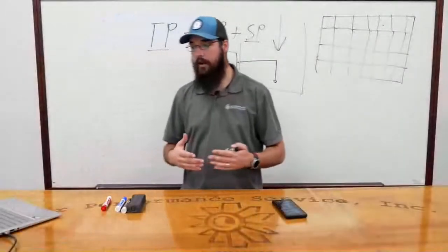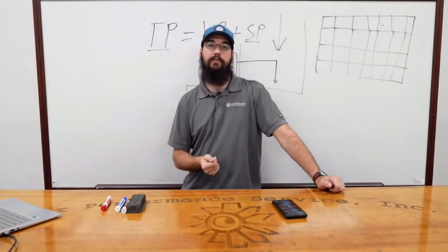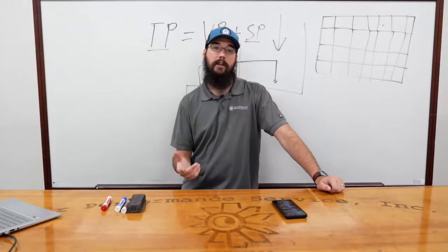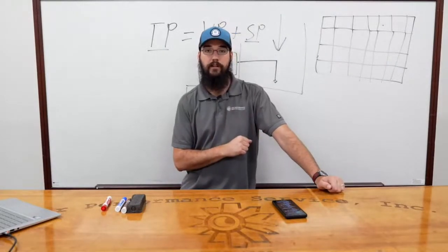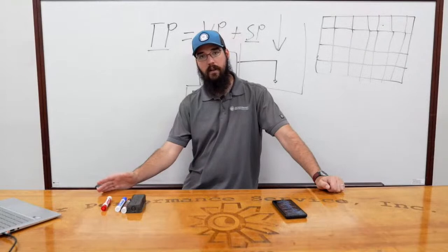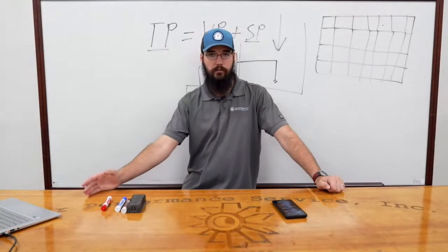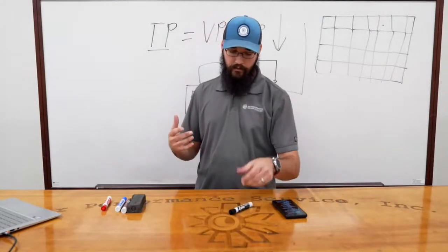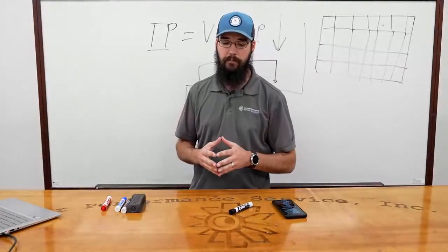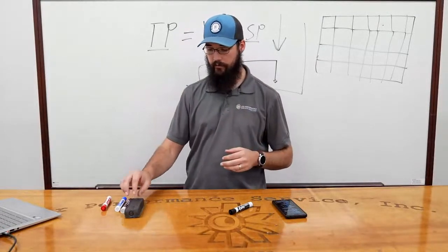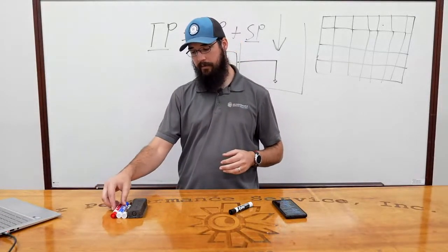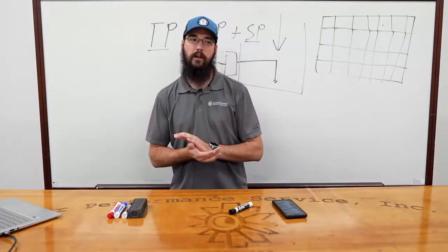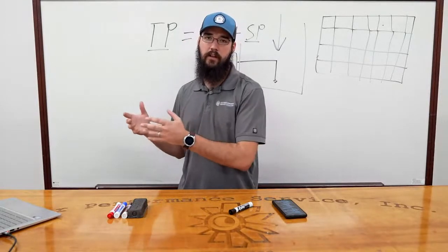Then you would be able to quickly identify that, okay, I have an airflow problem, and that explains why I'm having these readings. And you can eliminate a lot of other things that you have to troubleshoot. That's part of the point of taking a lot of readings. There is a philosophy to this of how many readings you spend the time taking versus starting to do more in-depth troubleshooting. And there is a difference, because we can troubleshoot a lot of things without taking a lot of extra readings.